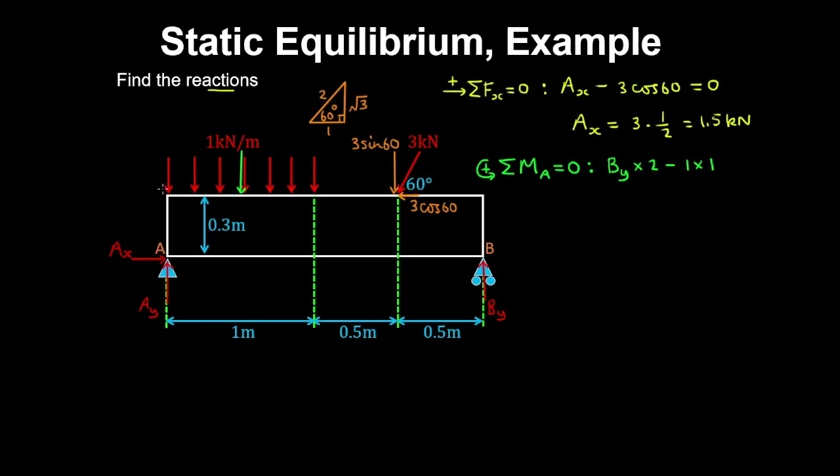And this force has a moment arm of 0.5 meters from the support, and produces a clockwise moment, so it's negative.